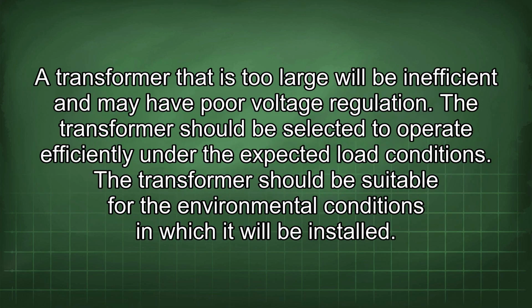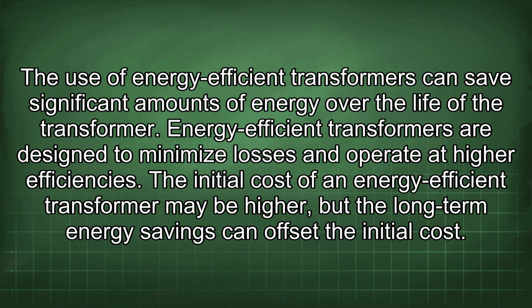A transformer that is too large will be inefficient and may have poor voltage regulation. The transformer should be selected to operate efficiently under the expected load conditions. The transformer should be suitable for the environmental conditions in which it will be installed. The use of energy-efficient transformers can save significant amounts of energy over the life of the transformer.